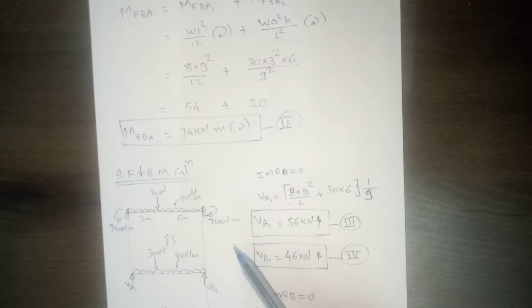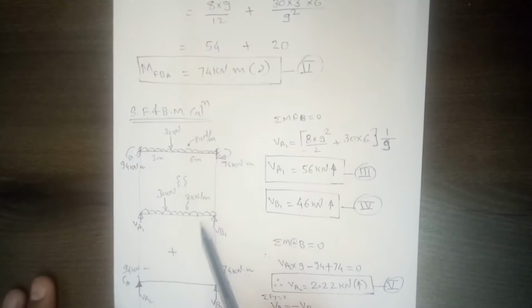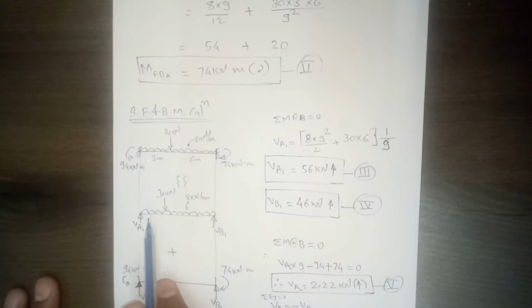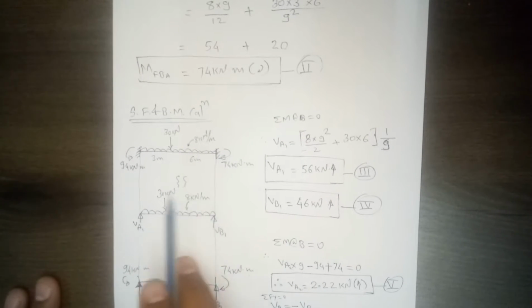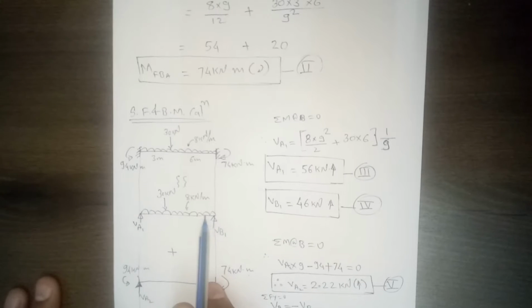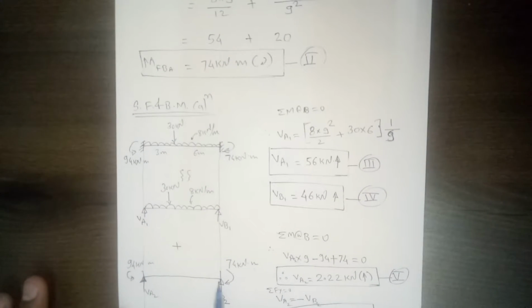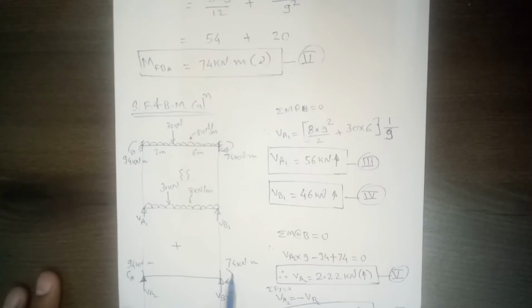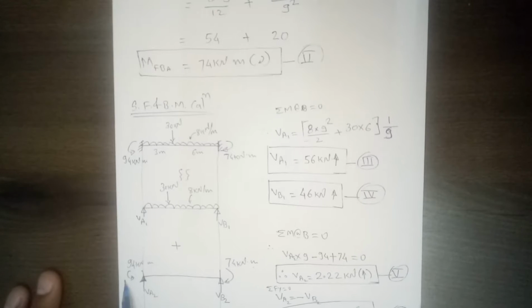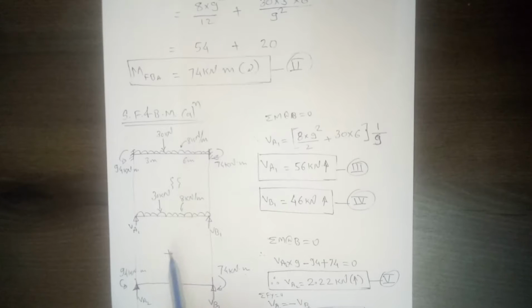But instead of doing that, we convert this problem into two parts. One with external load, which, if you remember, we call a released beam. So this is the released beam with external load, and then the released beam with end moments. We already know the end moments.